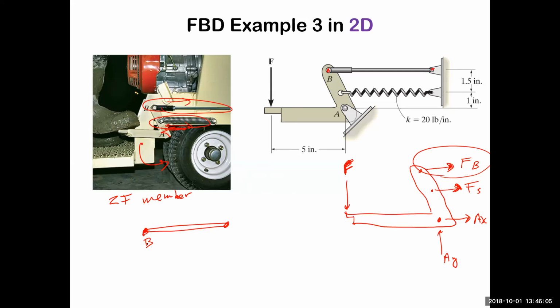Yeah, that cable is feeling the exact same force, because it's trying to be stretched out. When that foot is pressing on the pedal, we're putting tension on that spring and that cable. That cable wants to be stretched out. So that cable feels that same force that we drew as FB in the bracket diagram, but going in the opposite direction.